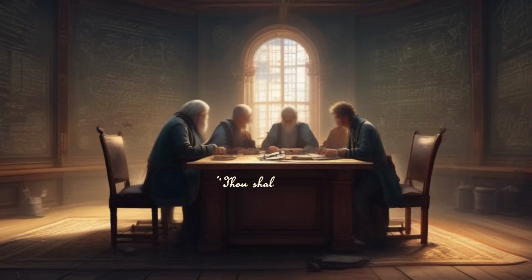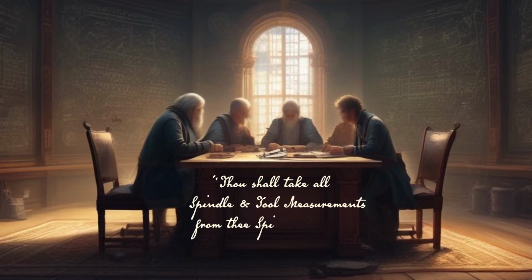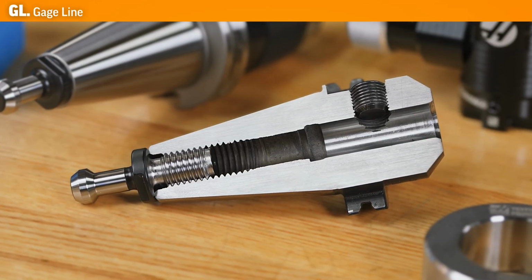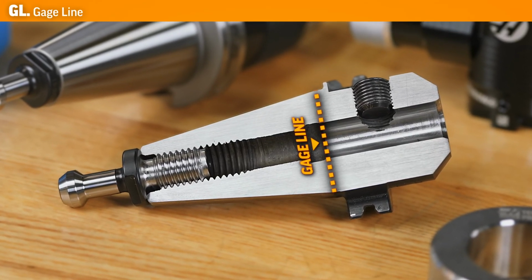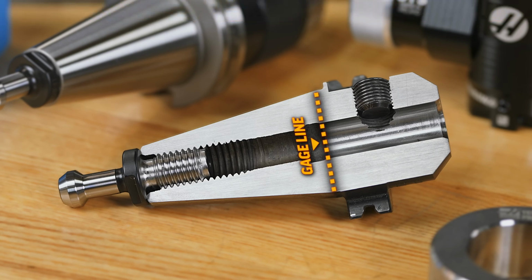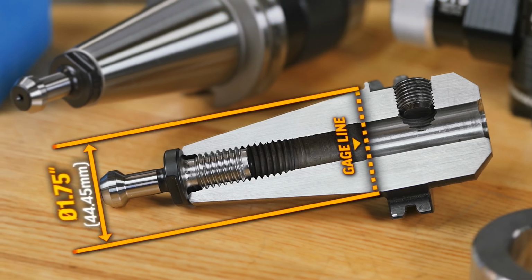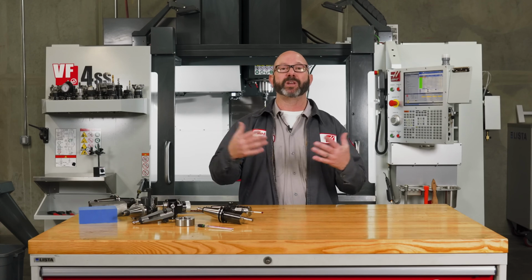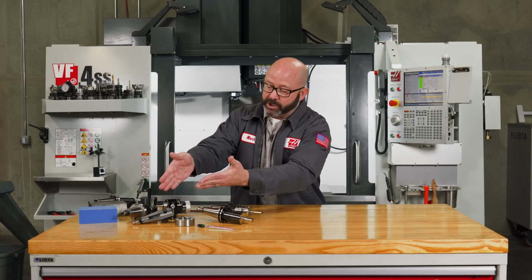To solve this problem and to make sure that everyone is on the same page, it was decided many years ago by some clever people behind locked doors that we would take all of our spindle and tool measurements from our spindle gauge line. Now, on this machine with a 40 taper spindle, our gauge line is a theoretical line that intersects our spindle or tool taper at exactly 1.75 inches, 44.45 millimeters in diameter. Now, this is a really difficult position to measure from, an imaginary theoretical line set in between two tapers.